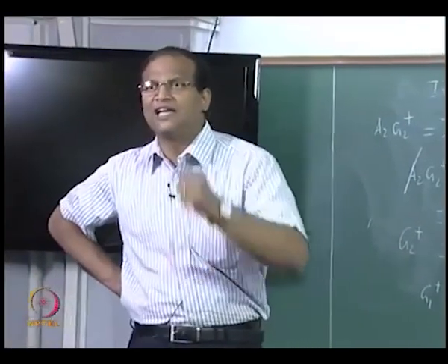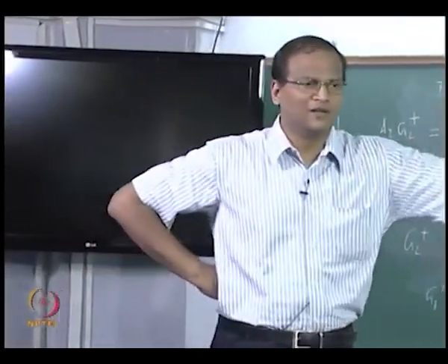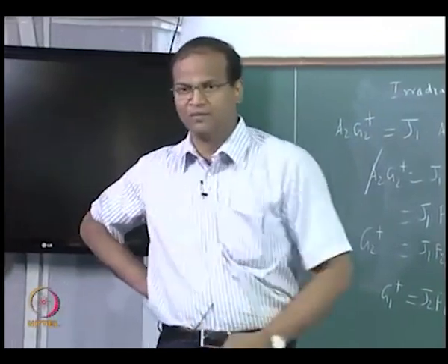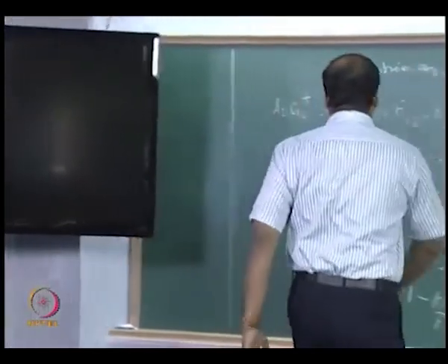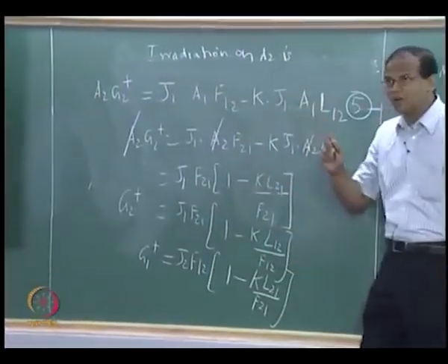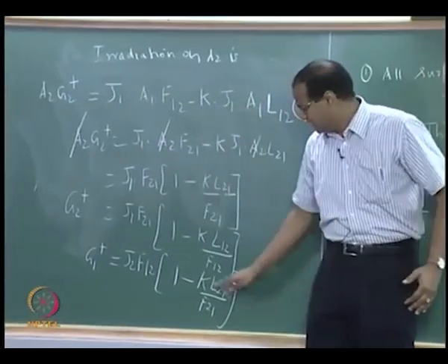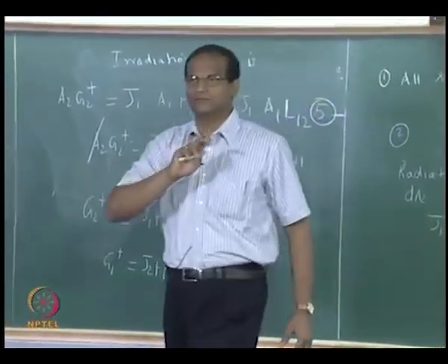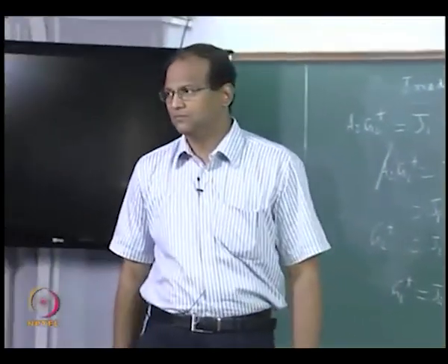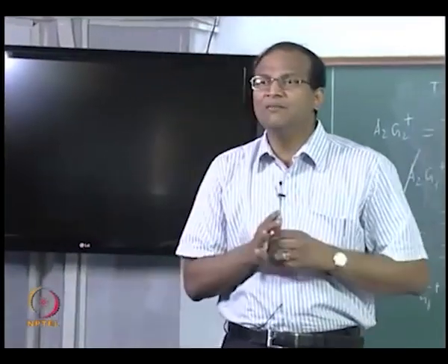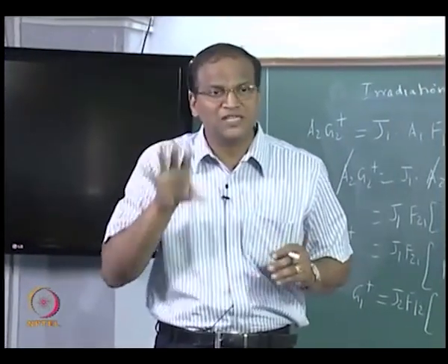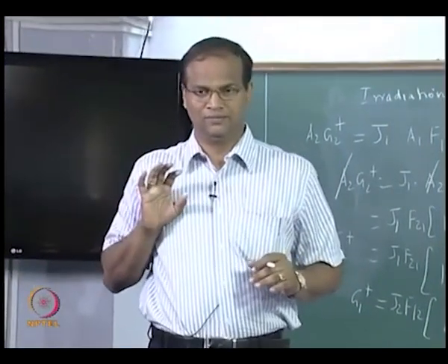If the transmittance of the gas is 1, then we have what is called the evacuated enclosure or transparent medium. So whatever is within the brackets will have a value less than 1 consequent upon the fact that kappa is not equal to 0.